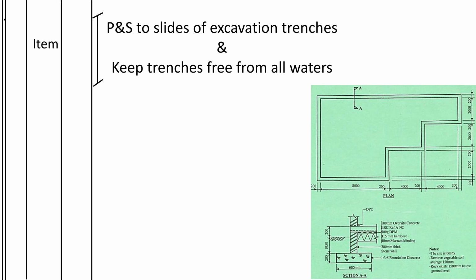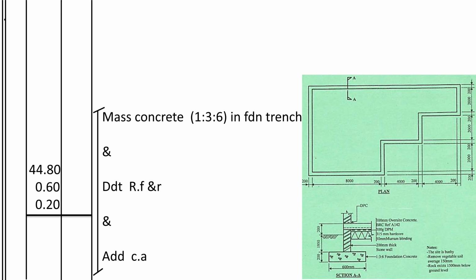after excavating the trench, we need to do planking and strutting to the sides of the excavation trenches, and also to keep the trenches away from water, dewatering the sites. This one, in our system, we write item. This one, we shall allocate a provisional sum in the bill of quantity using the SMM. Alright, then we shall go to mass concrete in the foundation trenches.